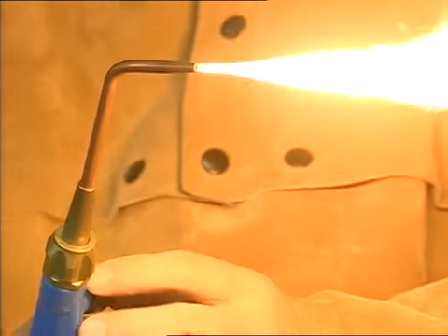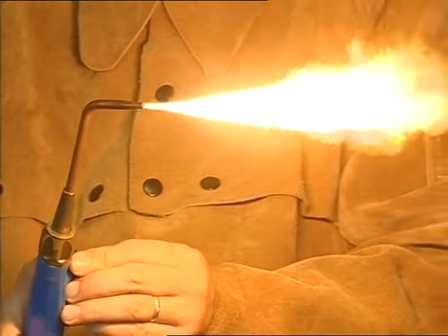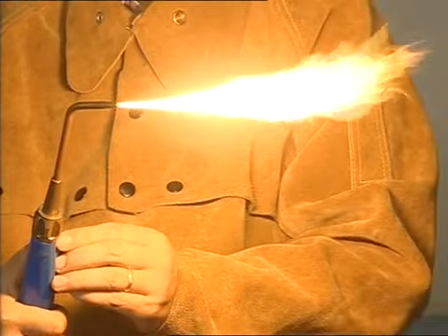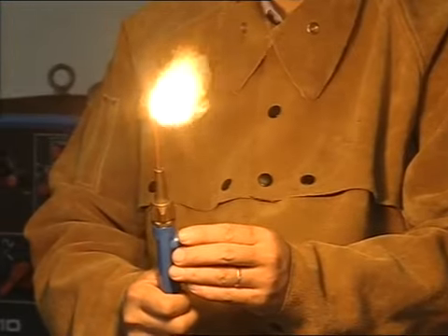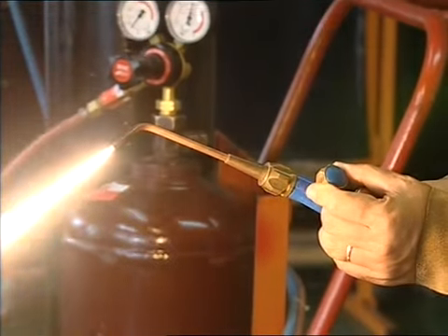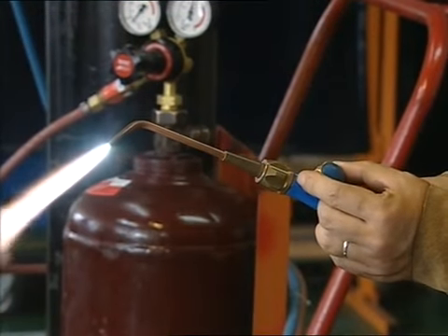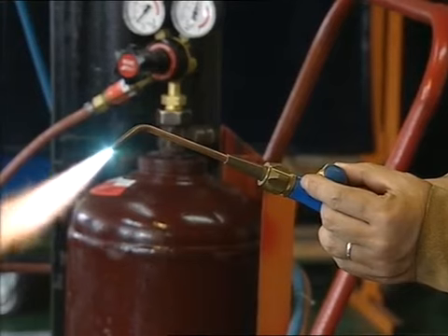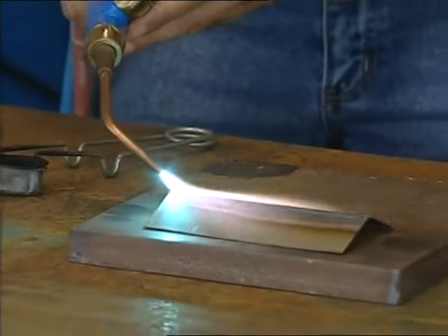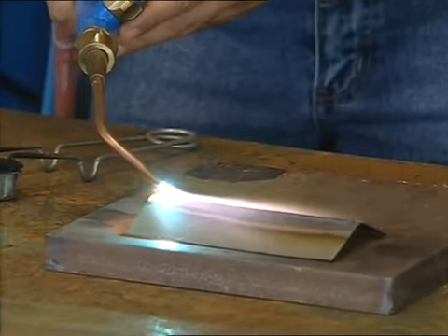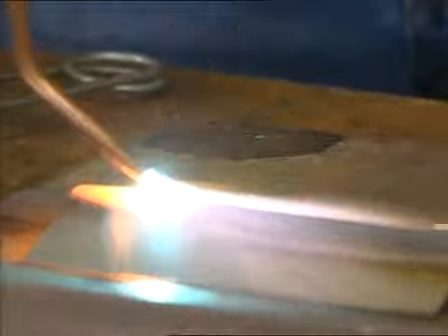Once it's connected to the gas and ignited, the acetylene that comes out burns in the air with a yellowish flame. Its temperature is relatively low. If we adjust the gas flow to allow more oxygen in, the temperature becomes very high. Using this extremely high temperature flame, workers can weld and cut steel plates.